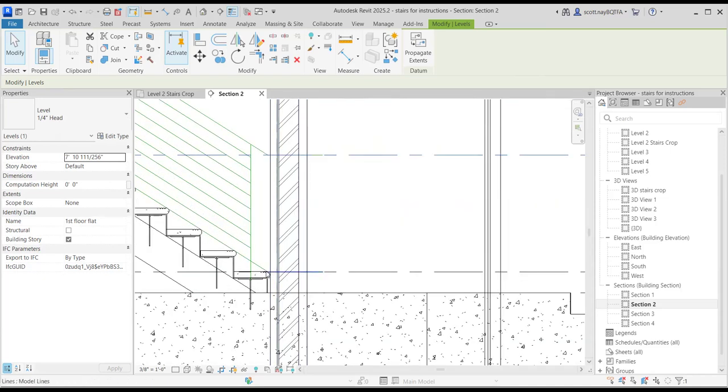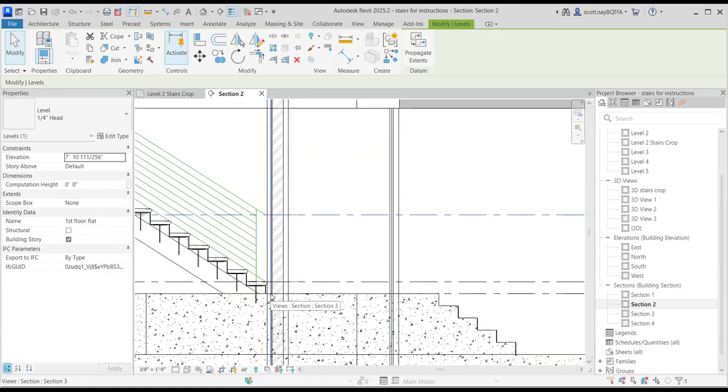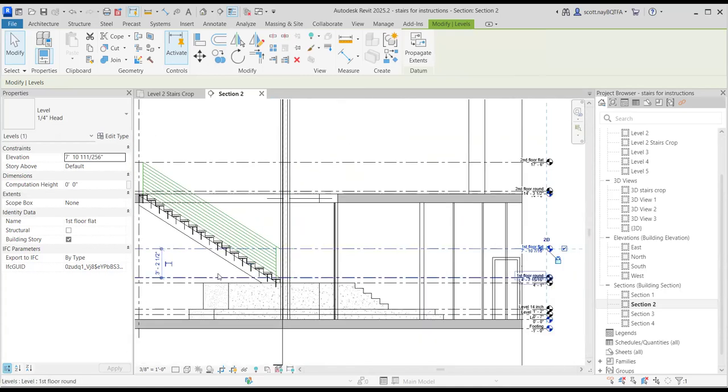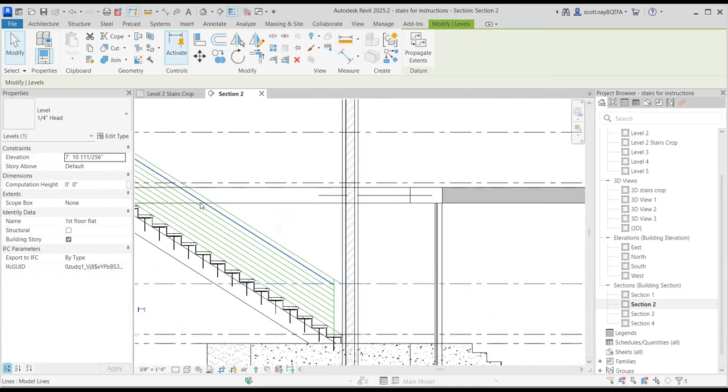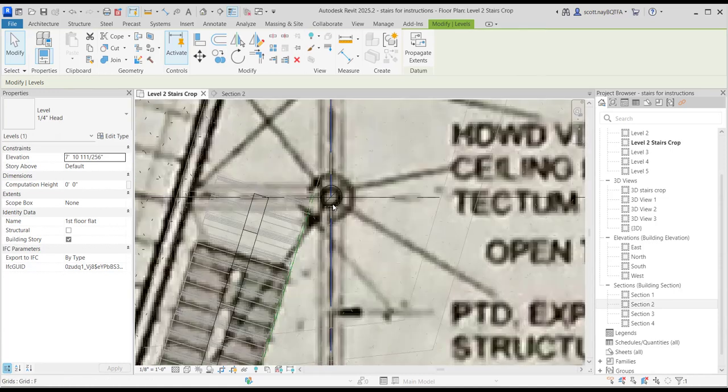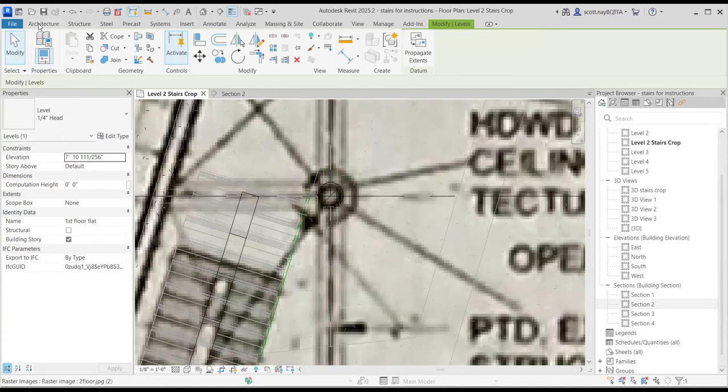First thing I'm going to do is complete this loop around here. I'm going to do it all for the lower railing first, and then I'm going to copy all those lines to the top railing. We don't need to redraw the 8 in between. Those are all going to be fine. So from up here, I need to go to architecture, model line.